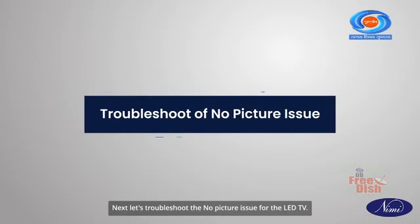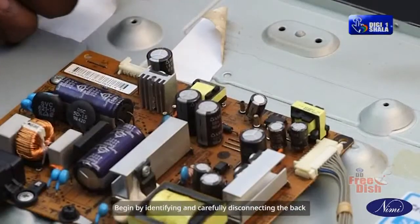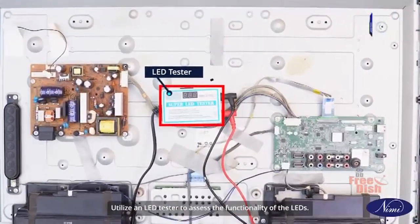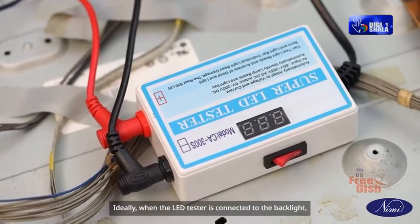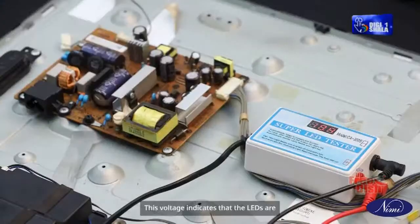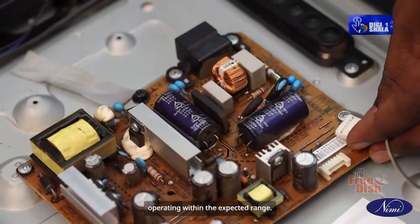Next, let's troubleshoot the no-picture issue for the LED TV. Begin by identifying and carefully disconnecting the back LED light connector from the power supply board. Utilize an LED tester to assess the functionality of the LEDs. Ideally, when the LED tester is connected to the backlight, it should display a voltage reading of approximately 72 volts. This voltage indicates that the LEDs are operating within the expected range.